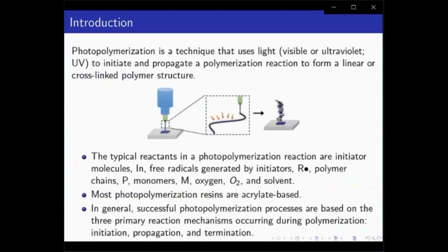Additive manufacturing stereolithography process works by focusing an ultraviolet laser on a vat of photopolymer resin. With the help of computerized manufacturing, the ultraviolet laser is used to draw a pre-programmed design or shape onto the surface of the photopolymer. Photopolymers are sensitive to ultraviolet light, so the resin is photochemically solidified and forms a single layer of the desired 3D object. This technique is called photopolymerization, and it has many industrial applications.